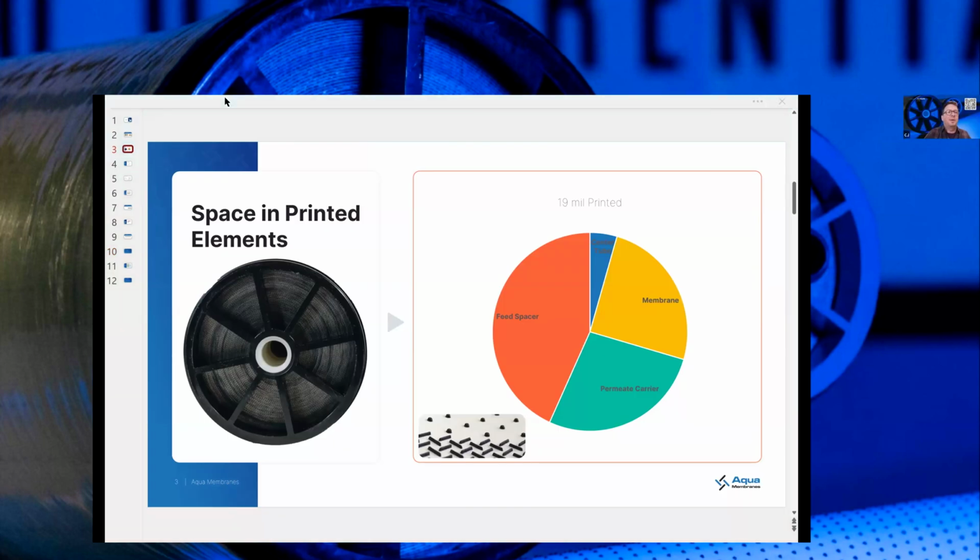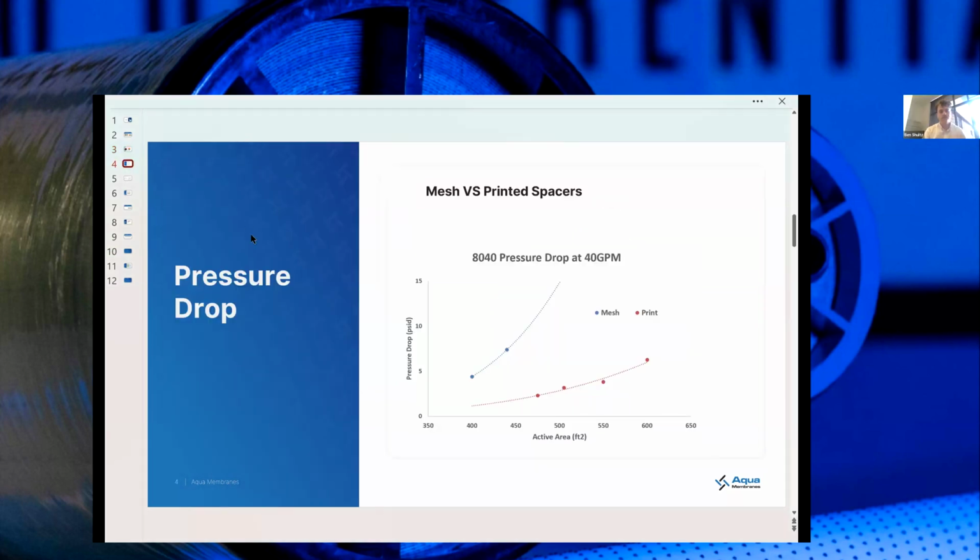Yeah. So that's quite a question. Let me pull that slide up again just for people to recall. So that's the slide here. The question is about the data as we start to go farther and farther down here. We do have data with thicker channels than we're showing here, a 20 mil print height. This is about a 22, 23 mil. We have made thicker channels, but the measurement of pressure drop gets to be difficult because it is such a low pressure drop.